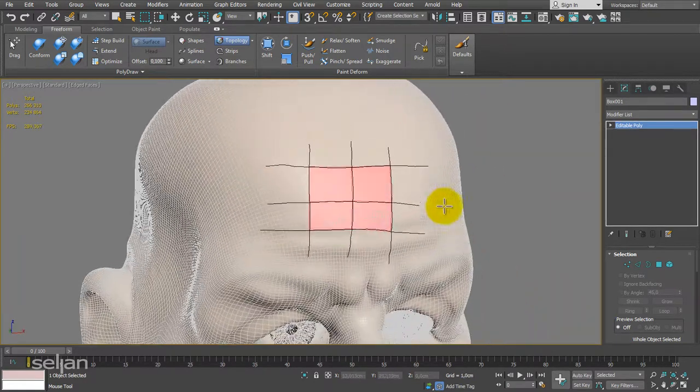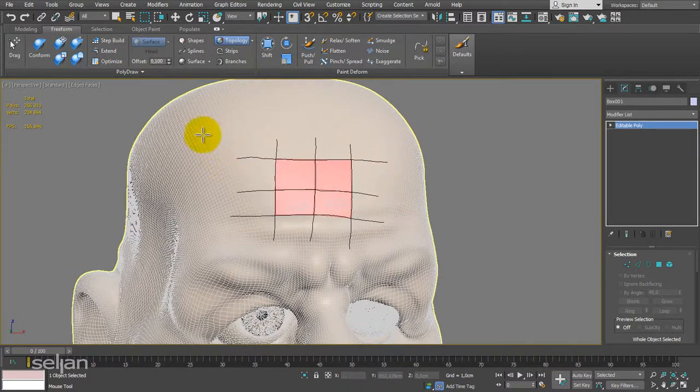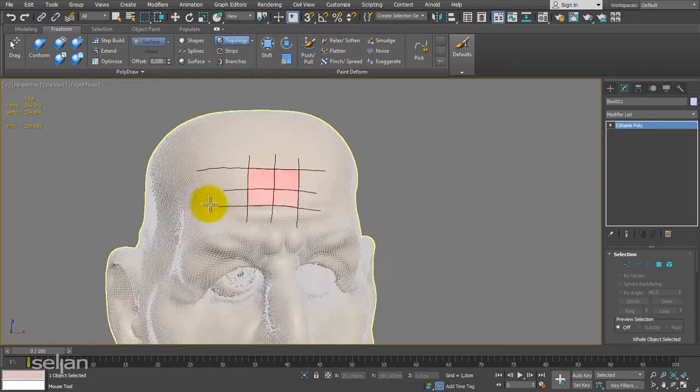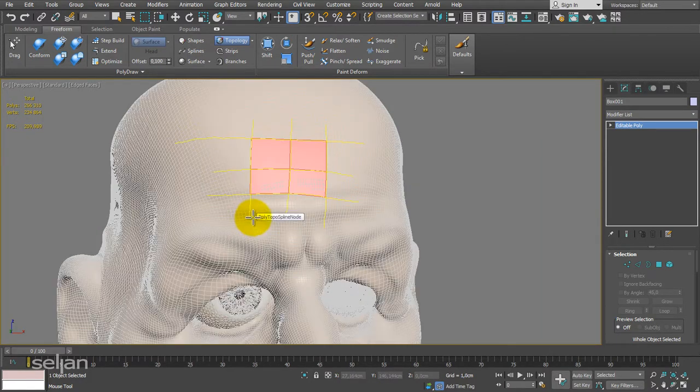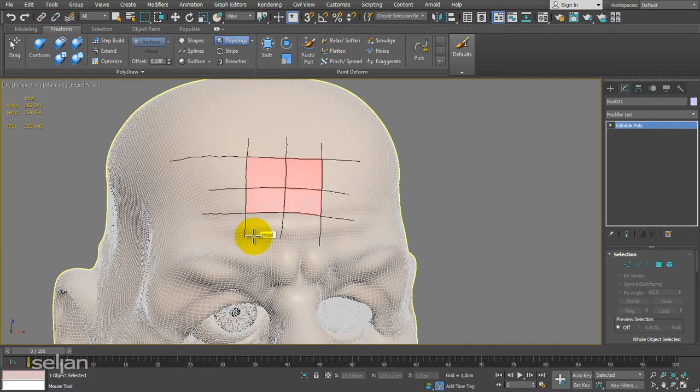A couple of lines. If you're doing these kinds of lines, it's not working. So it's not working that way. When you are holding down Control and clicking, that will remove an edge. So I will just make it here. If you're holding down Shift, then you can follow an edge. It is not super accurate, so it's not the best and fastest way if you want to create an entire topology, but it's very good and quite reliable to start with.